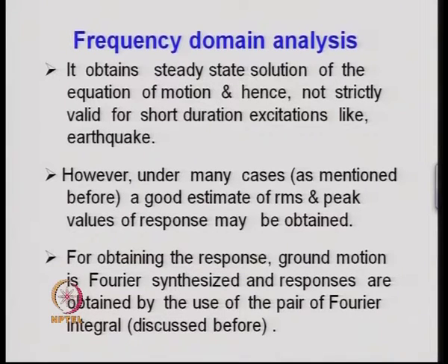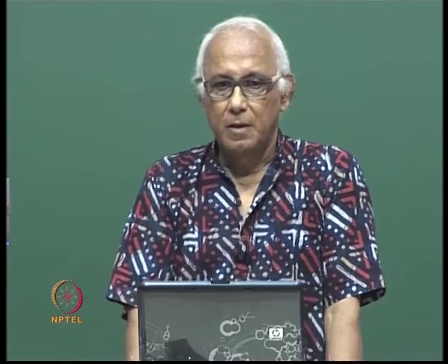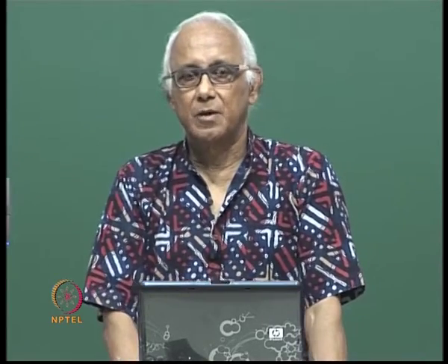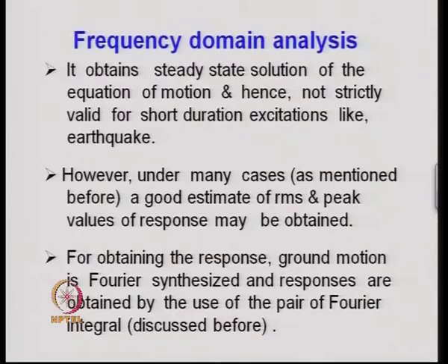Next, let us come to the frequency domain analysis. In the frequency domain analysis, the analysis is performed for the structure for a specified ground motion, and in that the input is the frequency contents of the ground motion. And how to obtain the frequency contents of the ground motion with the help of Fourier series and Fourier integral we have discussed before. Therefore, you know how to obtain the frequency contents of the ground motion. These frequency contents go as an input for the analysis.